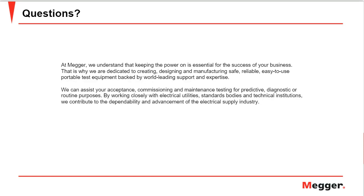So with that in mind, it's not for the protection of the transformer. It's more for the protection of the system that we use reverse power. Now, let's not confuse reverse power with directional protection, which is used more for coordination than for the actual implementation of a particular philosophy of protection.